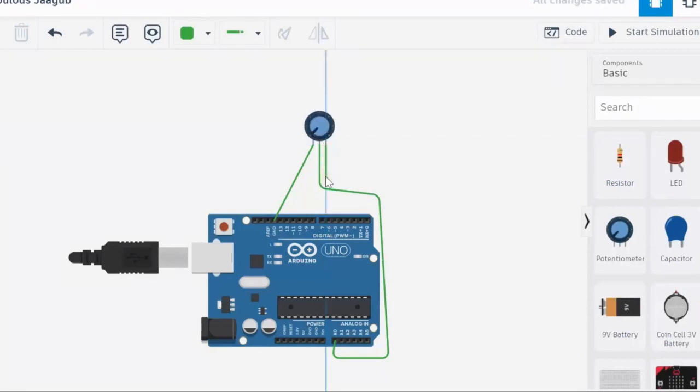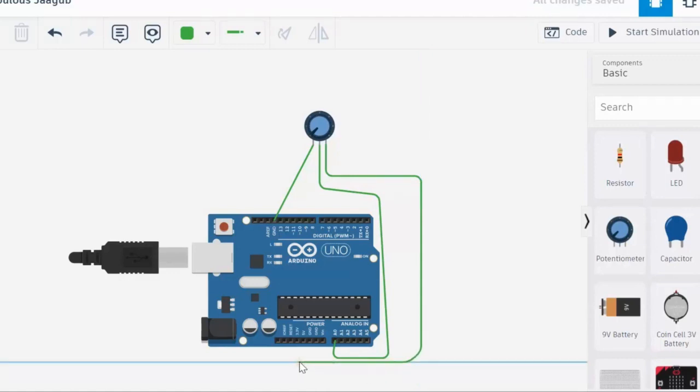Right now it is a variable resistance and we have three terminals. I will show you each of them in a while. We need to connect one to 5 volt. This is terminal 1, this is the common, and this is terminal 2. Resistance always varies between terminal 1 and the middle terminal, or wiper. Resistance will always be constant between terminal 2 and terminal 1. You understood? Resistance will vary between these two, or between these two. If I rotate the knob, resistance will increase between terminal 1 and common, and resistance will decrease between the other two terminals. Now it makes sense.